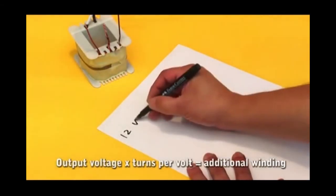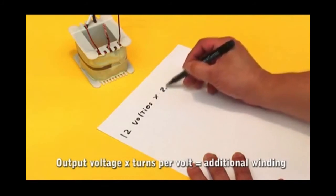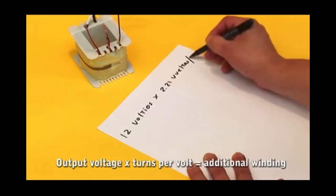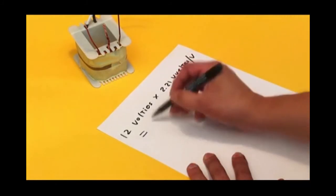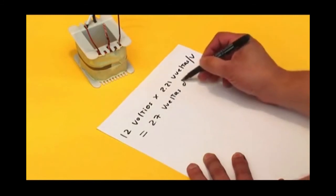The additional winding is 12 volts. To find the turns of wire, 12 volts is multiplied by the number of turns per volt. The result is 27 turns for the additional winding. This winding feeds a preamplifier, which will complement the power amplifier, with another transformer.